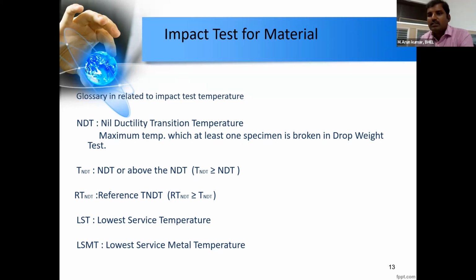So that is the reason why we are getting RT at very high temperature. In the code, there is a section in ASME, Section III NB, that is NB-4600, in which requirements are given for the heat treatment. There is a rate of heating and rate of cooling. They have given some guidance: the rate of heating or cooling at any hourly interval should not exceed 220 divided by the thickness in inches of the material being heat treated.